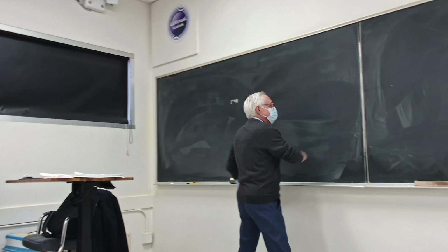You read hg. You read hf. Yes? You find x at 2. Knowing that you know h2, you know hg, you know hf, you have identified your final state for this throttling process, and you have dropped now the pressure to much lower ones.